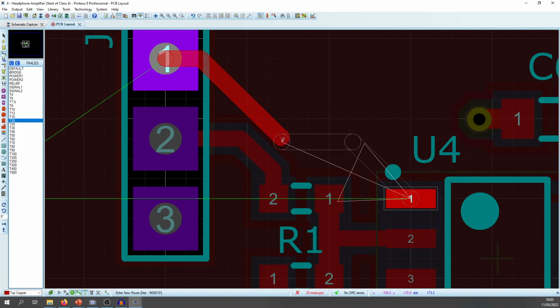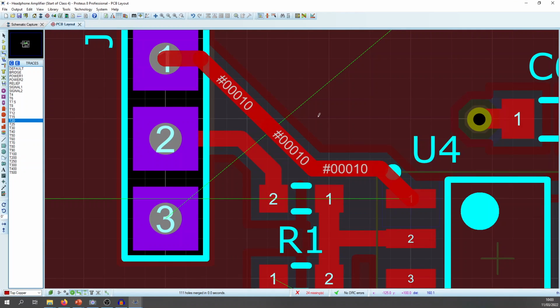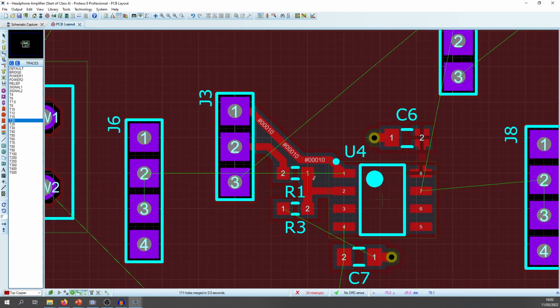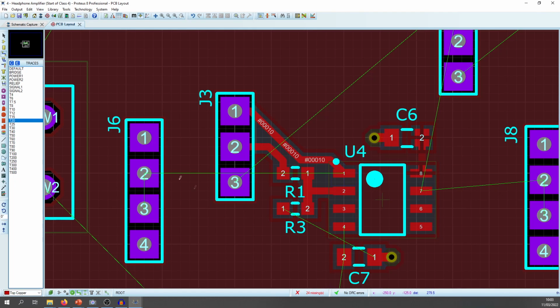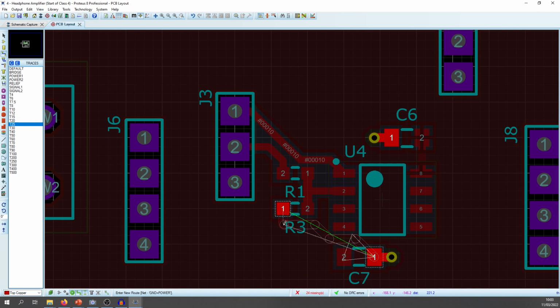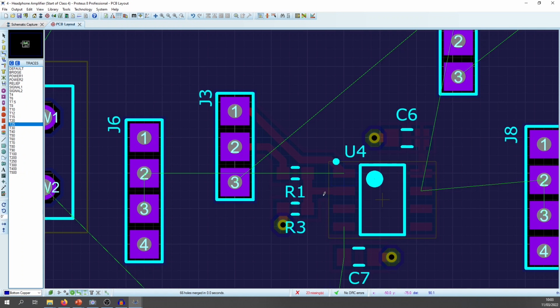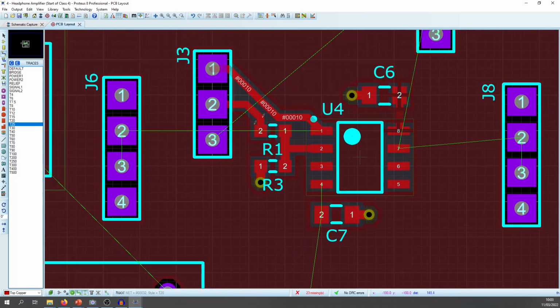Oh, when you've got that invisible sort of highlighting thing there, you can just press enter, and it'll just do the trace for you, if you want to take that trace. And then that is via, change the trace back to T25, larger, place it down. So you can get a feel that you can kind of untangle this stuff before you even place tracks down. That's really, really important. You want to untangle the nets as best as you possibly can before you start tracking.